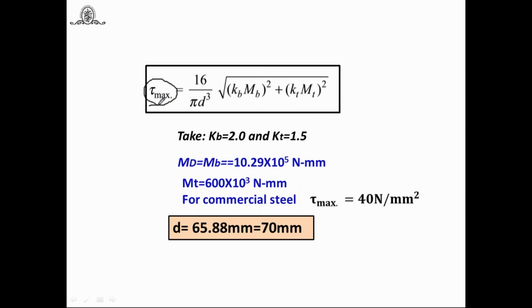According to the ASME code, it is 0.30 SYT or 0.18 SUT, but SYT is not given in this problem, and SUT is not given either. Remember this thing: in SPPU problems they have to provide this data. But in general, if it's not given, I have considered the shaft is made up of commercial steel, and for a commercial steel shaft you can remember and note down.